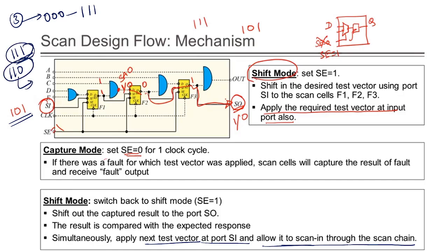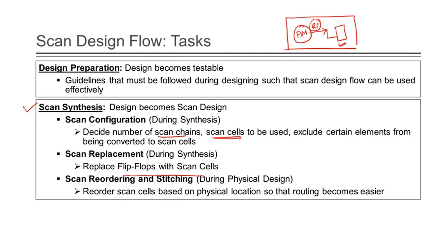Okay, scan design flow. Design preparation: you need to follow some guidelines so that the design becomes testable. These guidelines must be followed during designing, such that the scan design flow is used effectively. Suppose you have an FSM using asynchronous reset.